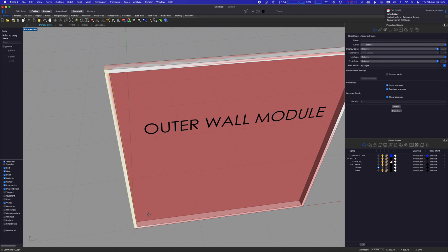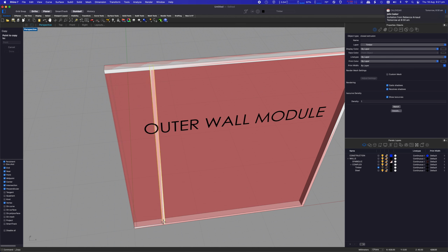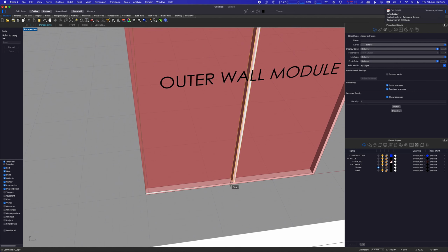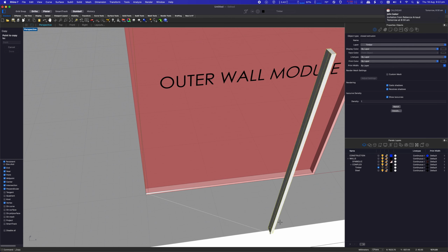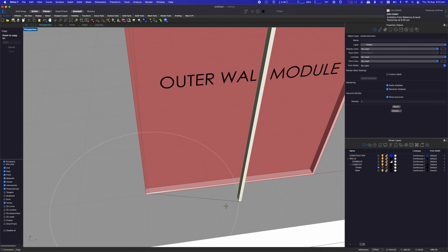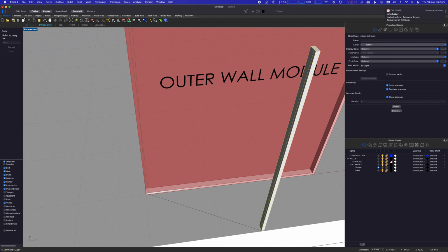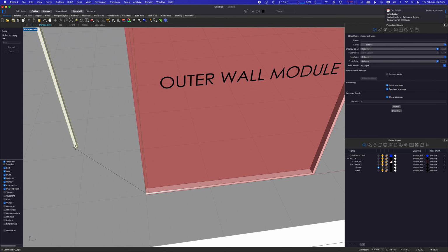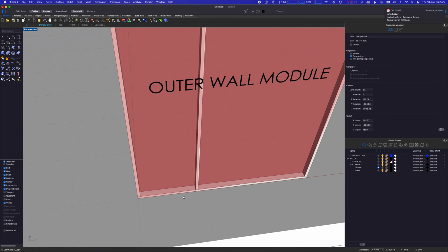Extrusion, copy from there. One thing, if you haven't already discovered it, the tab key locks the line at which you're dragging things along. So if you drag to a particular point and you want to stay on that line, like let's say we want to reference off this near line, I press tab, and now no matter where I move the cursor, it stays on that line. So we want to go 890 along there, and there we go.